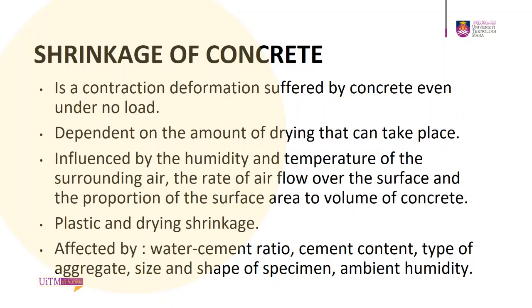So what is plastic shrinkage and what is drying shrinkage? Plastic shrinkage is due to the hydration of cement, which results in volume reduction. It is aggravated by loss of water by evaporation from the surface of concrete, particularly under hot climates and high winds. Drying shrinkage takes place after the concrete has set and hardened. It is due to withdrawal of water from concrete stored in unsaturated air void.